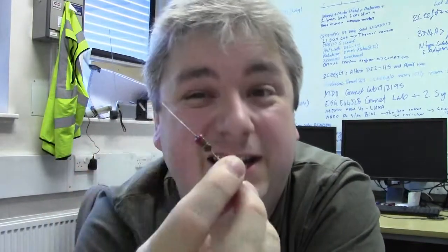So like I said, stick your head out from amongst the clouds, see what components are out there, and you will actually find those. Inductors do share the same colour coding as resistors, except instead of everything being in ohms, it's in microhenries. Capacitors are the same, you can get colour coded capacitors. And just for reference, this one here, not a semiconductor, that's a thin film resistor.